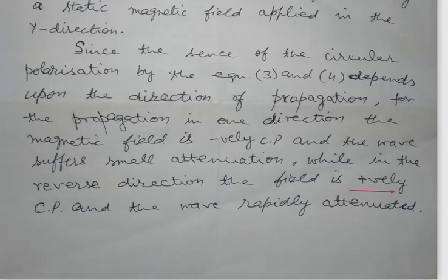So it is a very important device and is used in all microwave devices, and by using this ferrite isolator, the generator sees a matched load, meaning there will be no wave from the load towards the generator, and the generator sees that the entire power generated by the generator is delivered to and absorbed by the load.